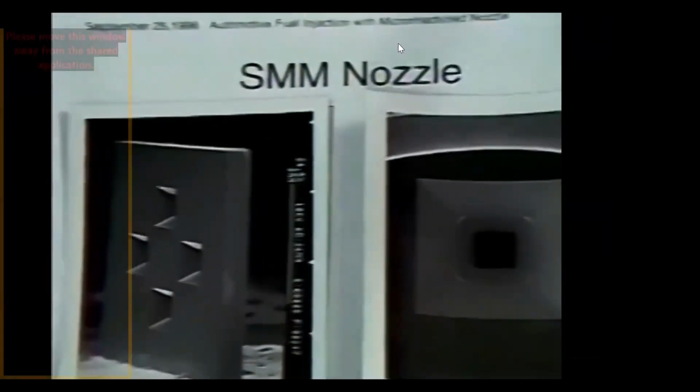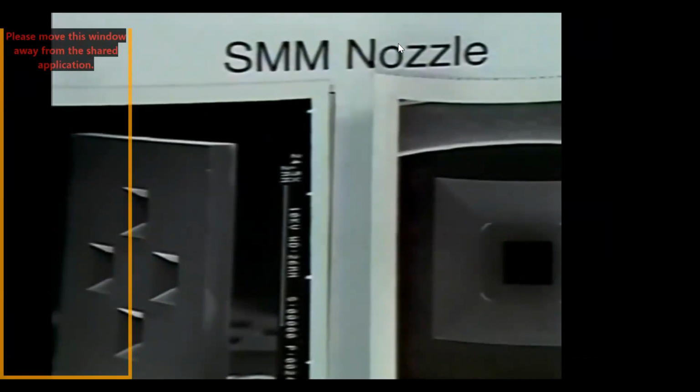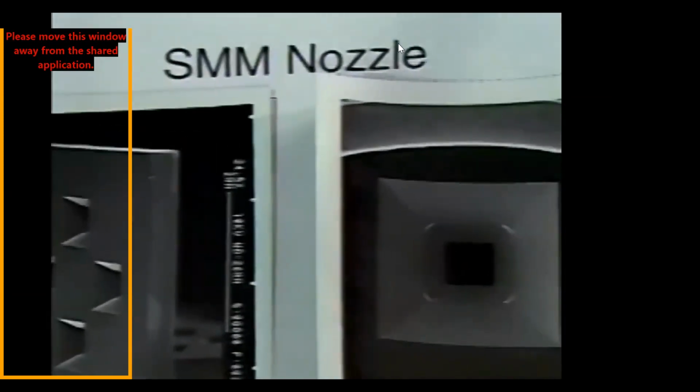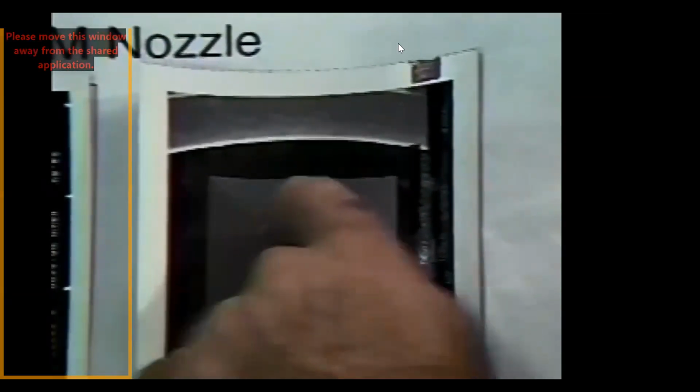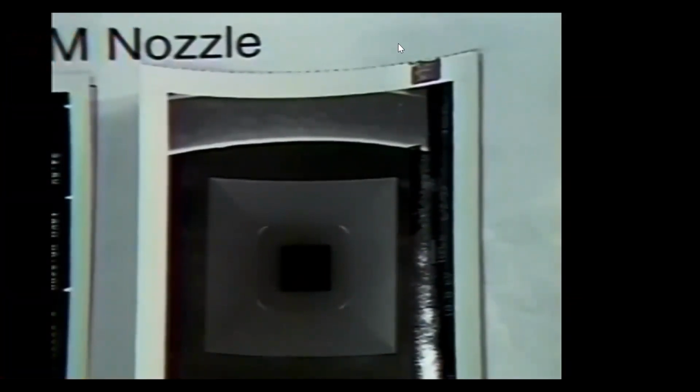This is a single piece of silicon, a single crystal, N-type. It's about 16 mils thick. There are 4 precision orifices etched in it in a single etch. We'll go over that process. The feature sizes might be difficult to see, but there are some very sharp corners on here. The feature sizes are controlled down to 70 nanometers.